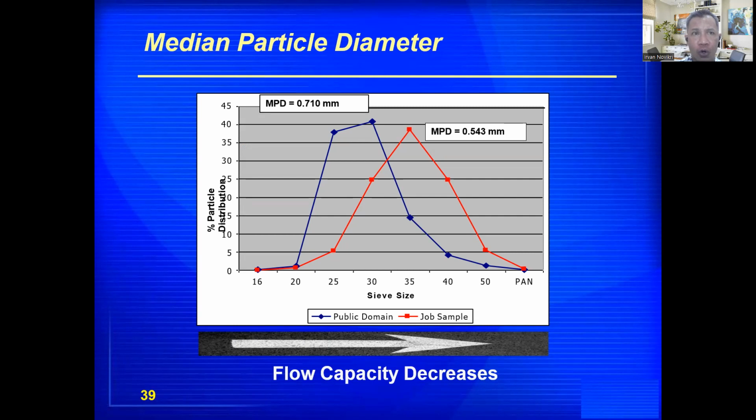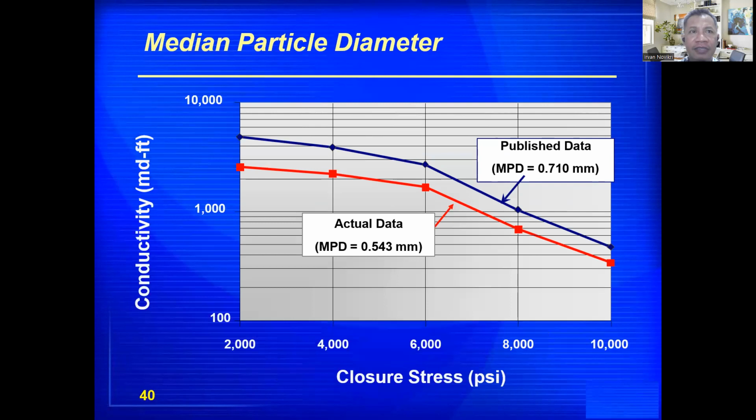Look at what happened to the conductivity. 0.16 or 0.17 millimeters is all the difference you have here. It's almost infinitesimally small, you could hardly even show it with your finger. Yet you got a complete twofold reduction in conductivity just by shifting the median particle diameter from the left-hand side of the size distribution to the fine side of the size distribution.